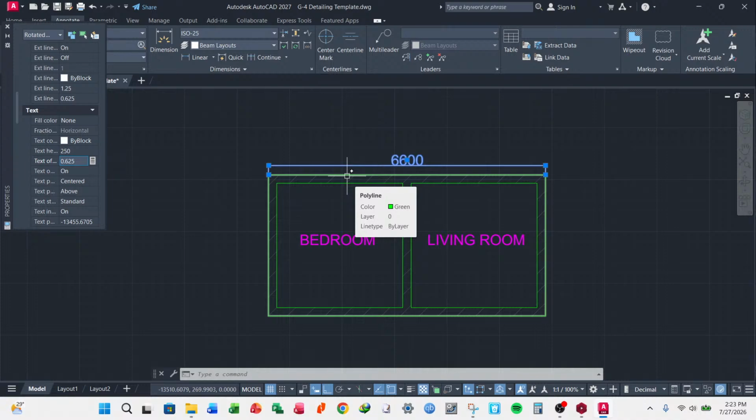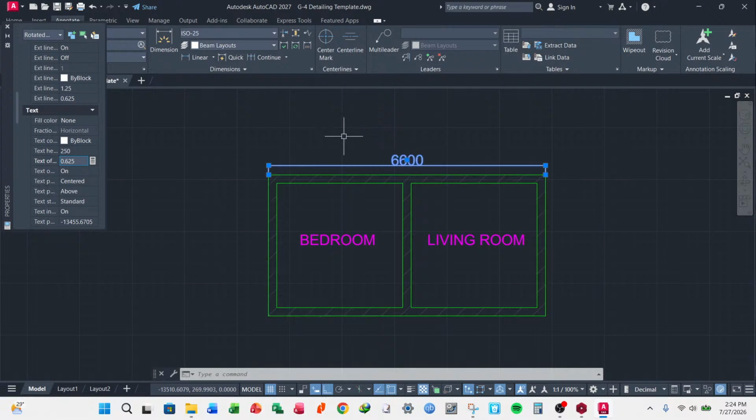So you can copy all these properties into a dimension style. Similarly, you can do the same to the text style. So you can create several styles of text and dimensions that will apply to the different objects. This will also vary with the scales of your object. So if you create different styles of dimensions and text that will match the different scales of your drawings.